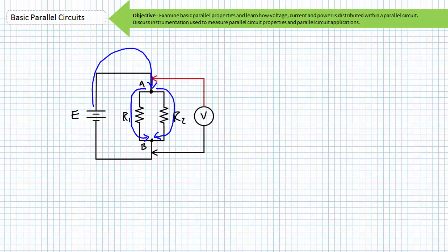Before we begin with a technical discussion of parallel relationships, let's just briefly examine the manners in which such relationships can be depicted in schematics. Again, one of the most useful techniques I've found in teaching basic circuit analysis is to view the circuit from the perspective of flowing current. As current enters a node, ask yourself, does current have a choice of paths? And if so, how many choices? If there exists no choice, the elements connected to this node are in series with one another, and there exists one path. If there exists a choice, the branches connected to this node are in parallel.